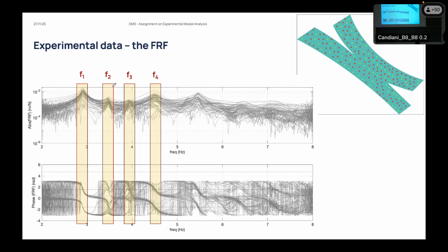Why are we interested in those ranges? Because, as I was saying at the beginning of the lecture, what we can do is approximate the behavior of the structure with the resonant mode just in the neighborhood of the natural frequency. Considering a larger span would imply also having the contribution from other modes.